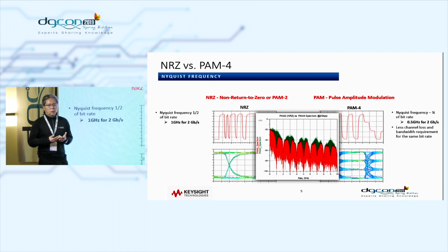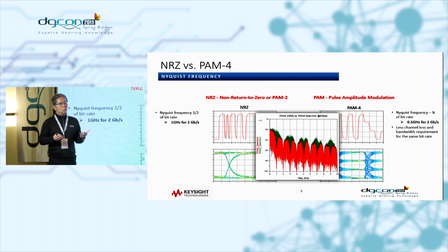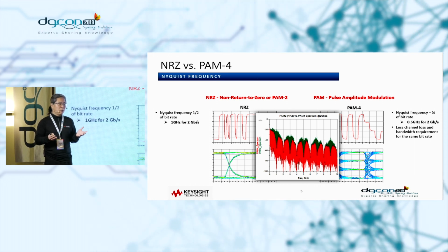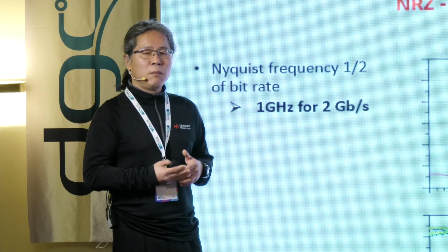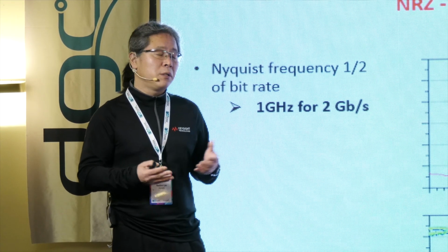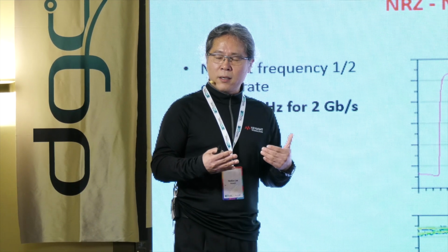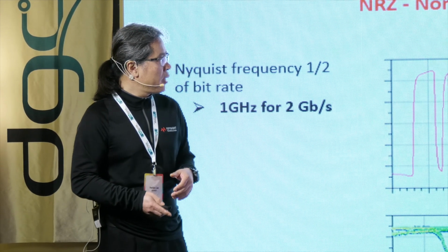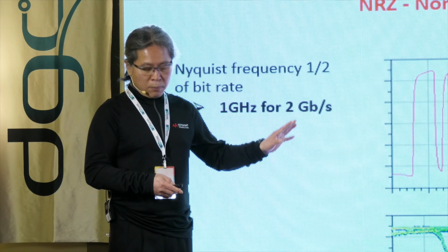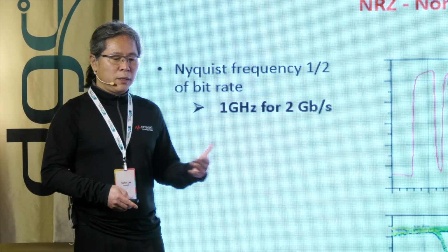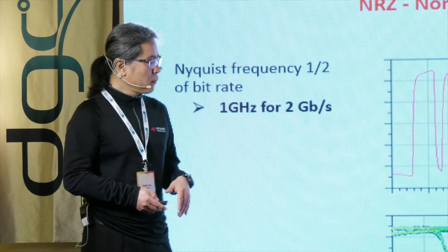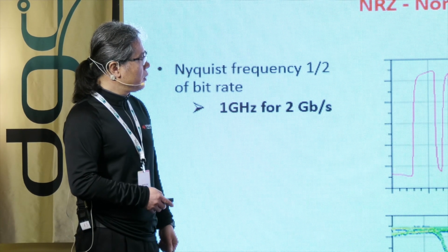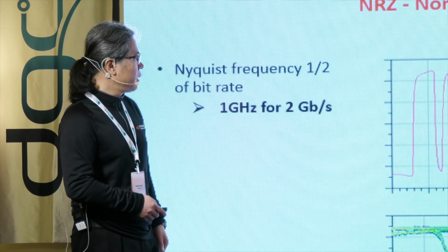As you probably know, for FR4, there is a rule of thumb of about 0.1 dB loss per inch per GHz of frequency. So if you are using the same formula but reducing the frequency range, you can think, yes, I can get smaller loss. That means you can make the design much more efficient. That is one of the reasons why people are using PAM4: sending a higher bit rate of data with the same channel structures or size of the transmission lines.